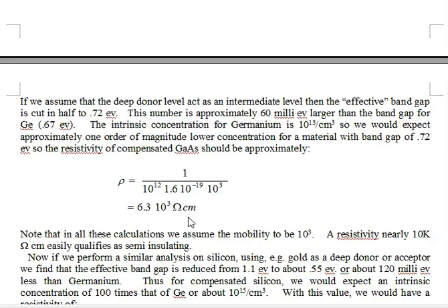And why is that good? Because we can basically use the gallium arsenide as a circuit board. We can put lines right on the gallium arsenide. Were it not semi-insulating, any line that we'd put would be shorted. But if it's semi-insulating, we can put lines as close to one another as we can, and we can be quite confident that those lines will not short one another out.